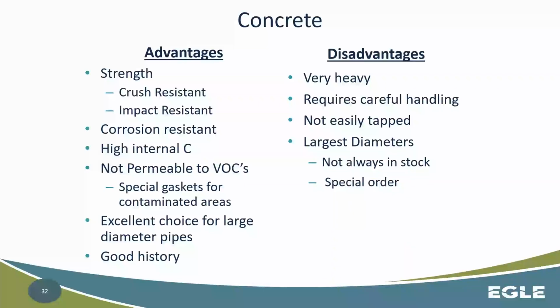Disadvantages here, it's obviously very heavy. It's concrete. It's gonna weigh quite a bit. Requires careful handling, and the installation process is going to be much more difficult. In terms of that, you're going to need special equipment, things like that. They're not easily tapped, although they're usually not really meant to be tapped, because you're not putting an individual house right off of the 64-inch concrete main, or 10-foot concrete main or something like that. So it's a little different.